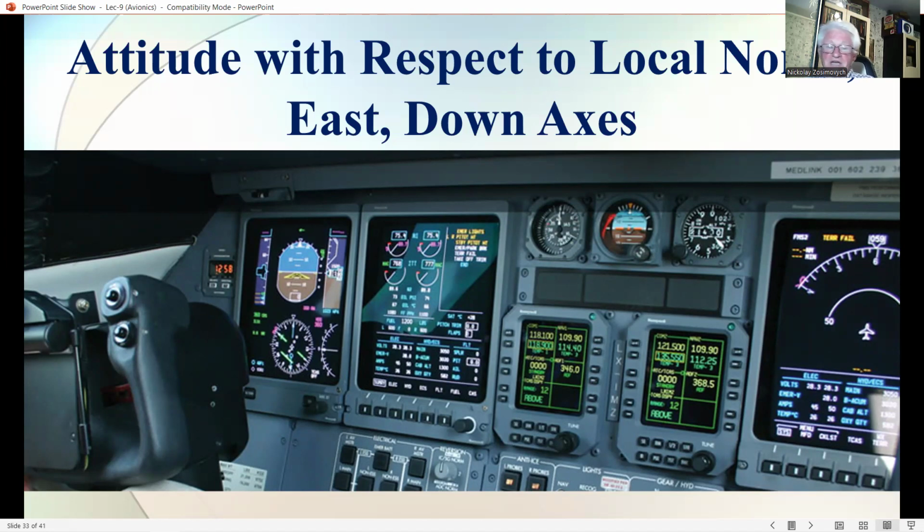The aircraft heading angle is generally required with respect to true north, that is the direction of the local meridian pointing towards the North Pole. The local meridian is a circle around the Earth which passes through the North and South poles and the aircraft's present position. It is therefore necessary to convert the gyro-derived data, which is with respect to inertial axes, to an Earth reference axis frame.